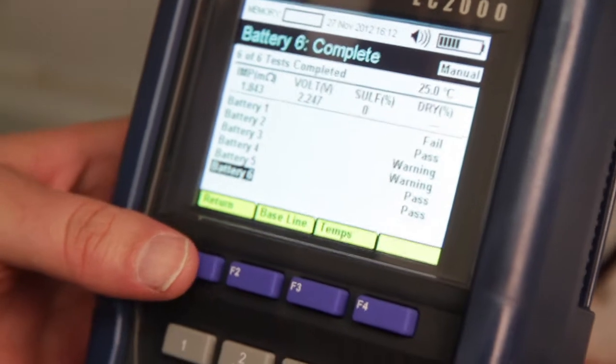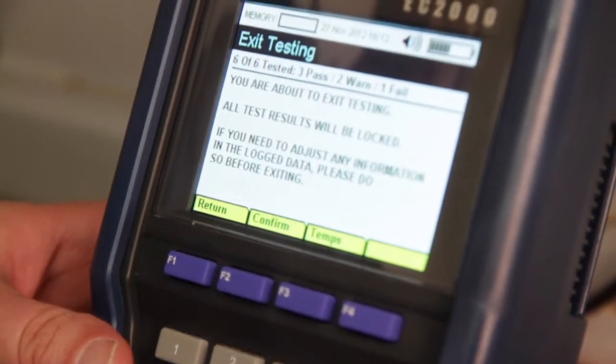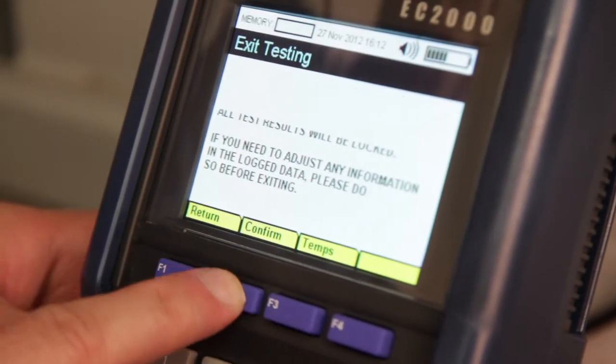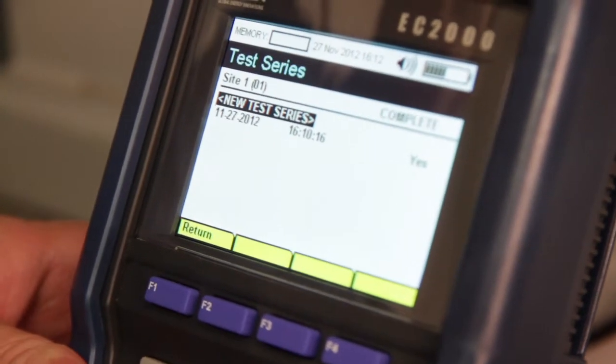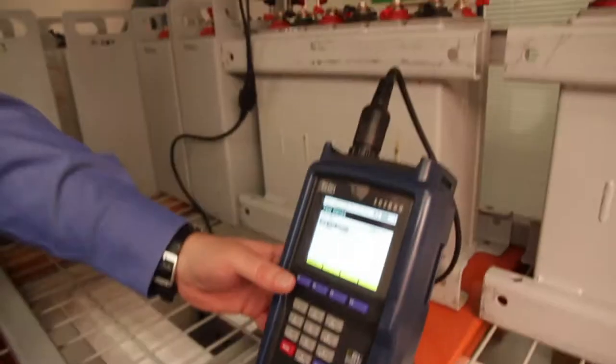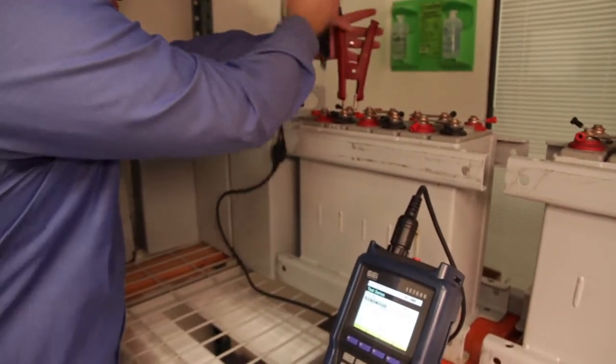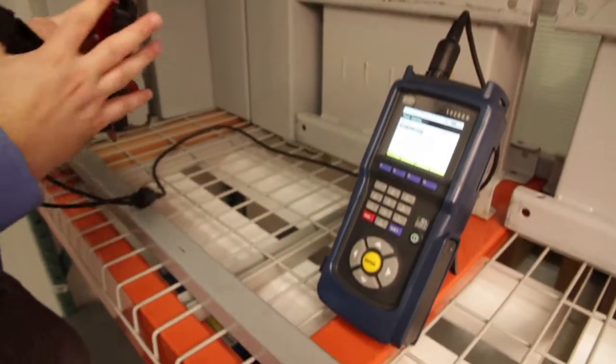Incomplete means that all the batteries in the string were not tested. Also note that it is necessary to complete the first test to establish a definitive baseline. Not completing the first test, however, will prevent you from seeing baseline-based values such as impedance percentage and cell scan values in both the analyzer and IBMS.